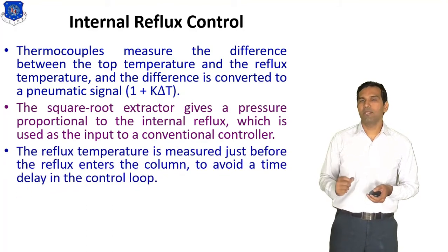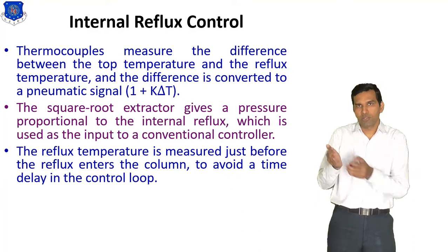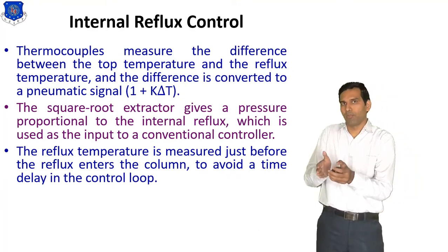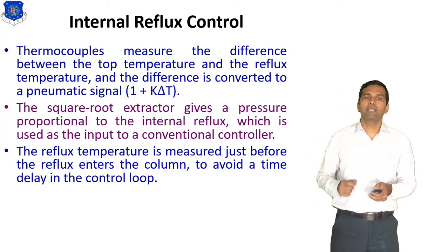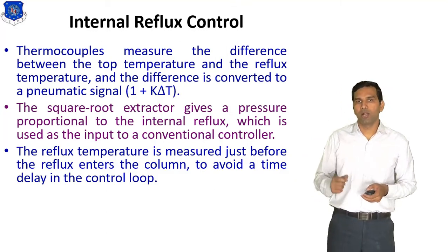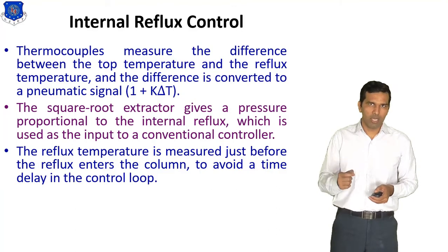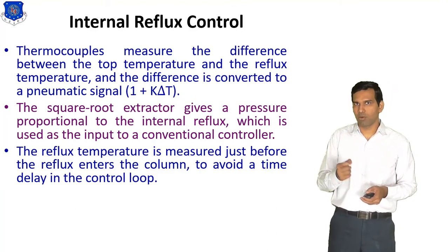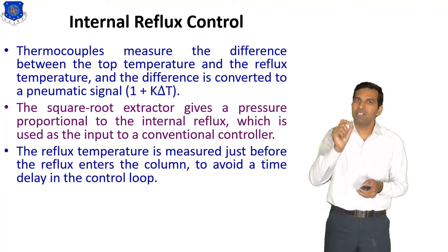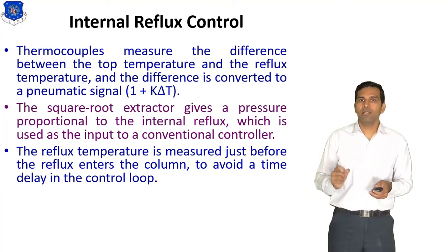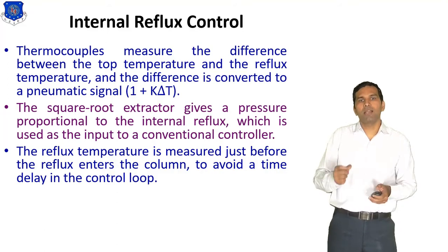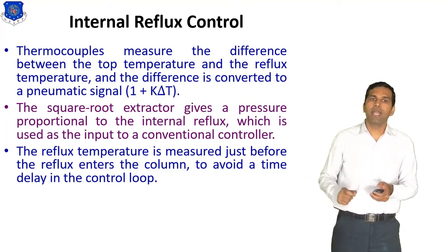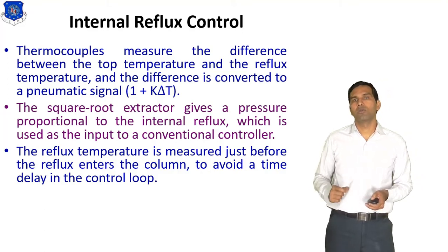The reflux temperature is measured just before the reflux enters the column to avoid a time delay in the control loop.